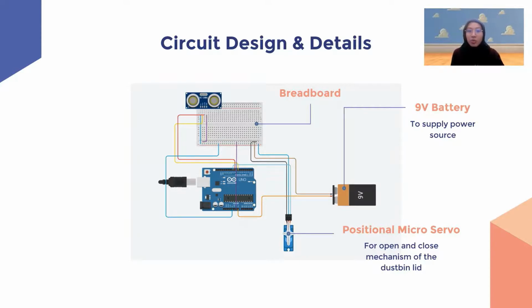Initially, the dustbin lid was positioned at a 0-degree position as the lid was closed. When an obstruction is detected by the ultrasonic sensor, the controller checks to see if it crosses a threshold distance value defined for the dustbin lid to open. As the sensor recognizes the presence of an obstacle or object, the controller will trigger the servo motor and the dustbin lid will open, but only for a limited time as programmed in the system coding.